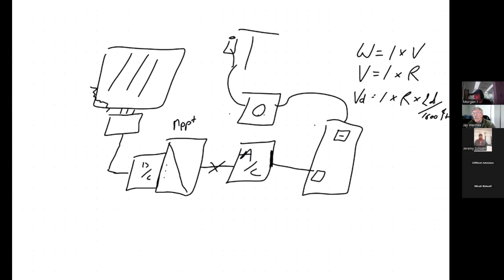So if I look up in the table and it tells me that 10 gauge stranded copper is 1.24 ohms, that's ohms per 1,000 feet. So what portion of 1,000 feet am I talking about? The table that I'm referencing is on page 92. So why do we say twice the distance? Well, it's a circuit. So there's wire there, wire back. So that's how far the electron is running.